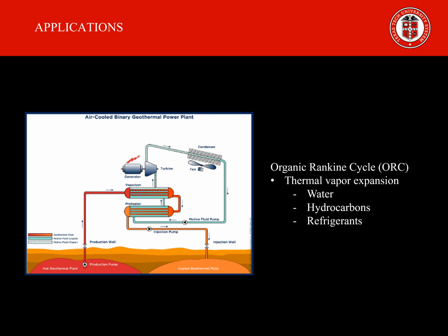The final application I will cover is the Organic Rankine Cycle, otherwise referred to as an ORC. Rankine cycles are a great way to extract power from expanding fluids, whether it be from a temperature or pressure differential. Vaporizing a liquid consequently expands it to become a gas. Typically, Rankine cycles vaporize water into steam. ORCs vaporize organic fluids, hydrocarbons like butane, or refrigerants, because they boil more readily.